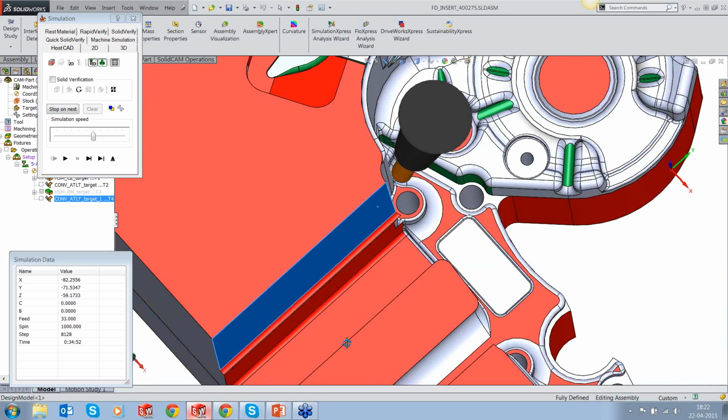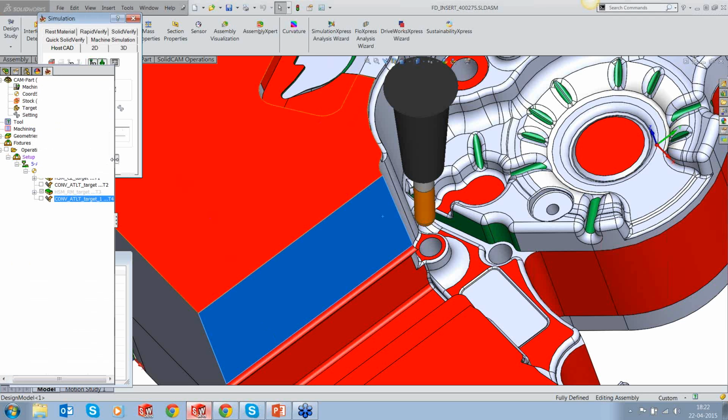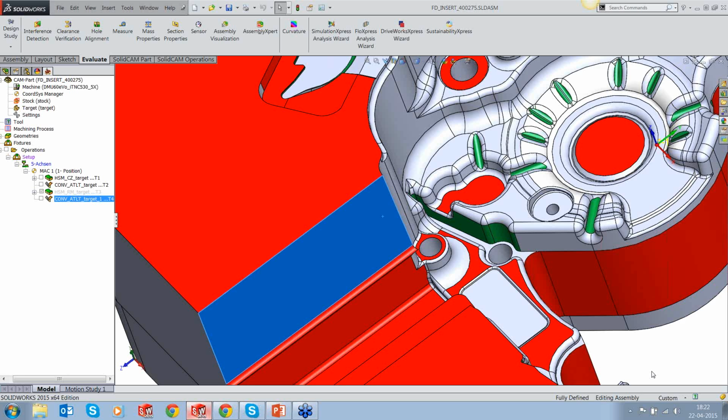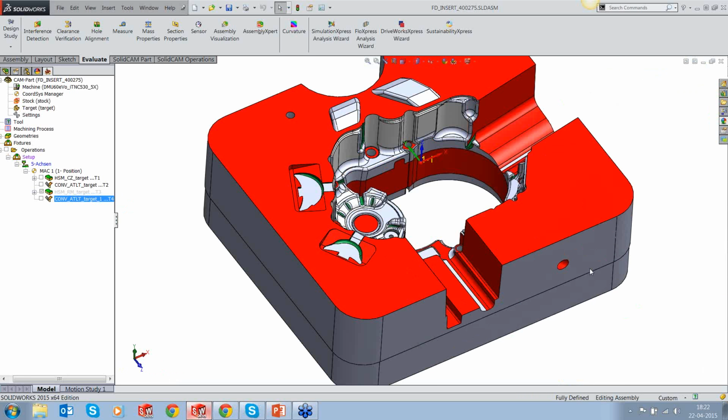machining. Very, very important feature, especially when you're doing large dies and you would like to move into the area using shorter tools and keep the toolpath gouge free. So it's very nice feature, and most important, it's completely automated. That means it doesn't need much of user's intervention. All they need is to provide the old toolpath, and it converts to 5-axis.